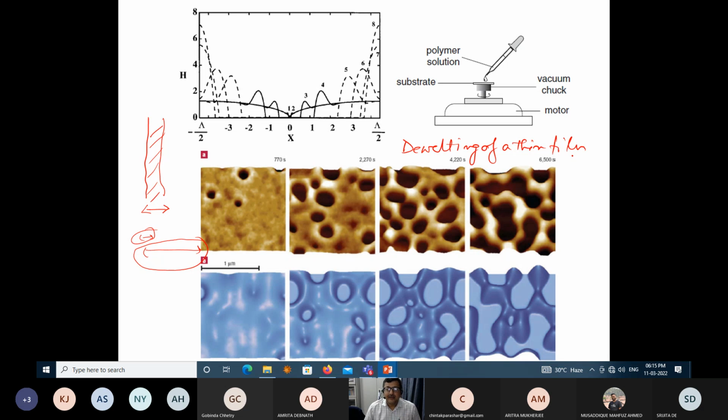Okay. What do you mean? That, you were expecting this was supposed to form a continuous film. But then there's some reason because of that, this did not form a film, but this started forming the holes, and these holes they grew. These holes they coalesce, and they form a kind of disintegrated film. Now, from here to here, the whole purpose of coating is lost.